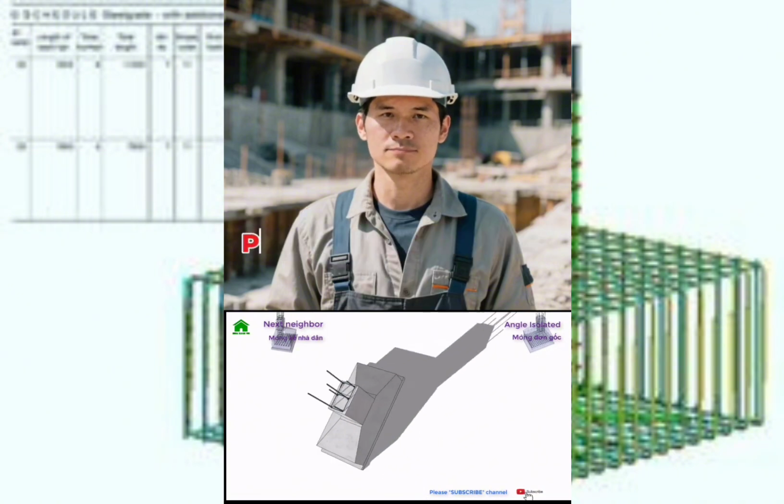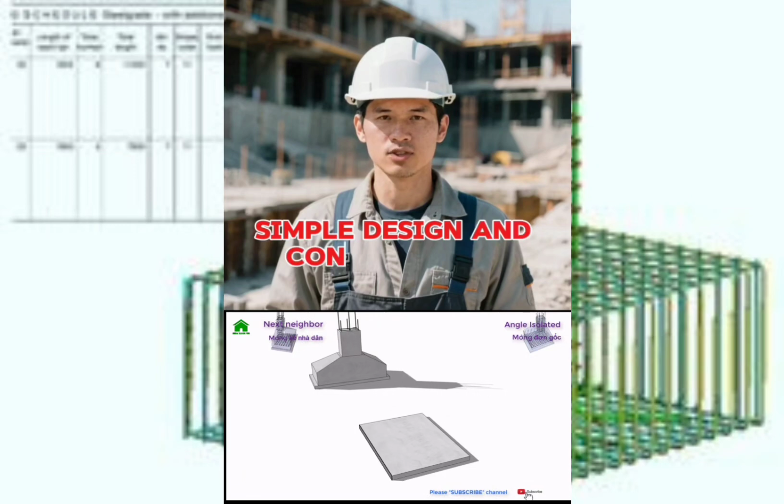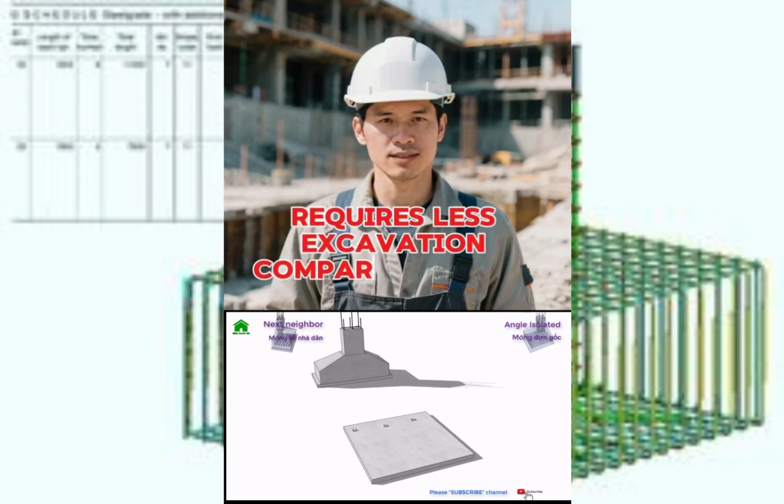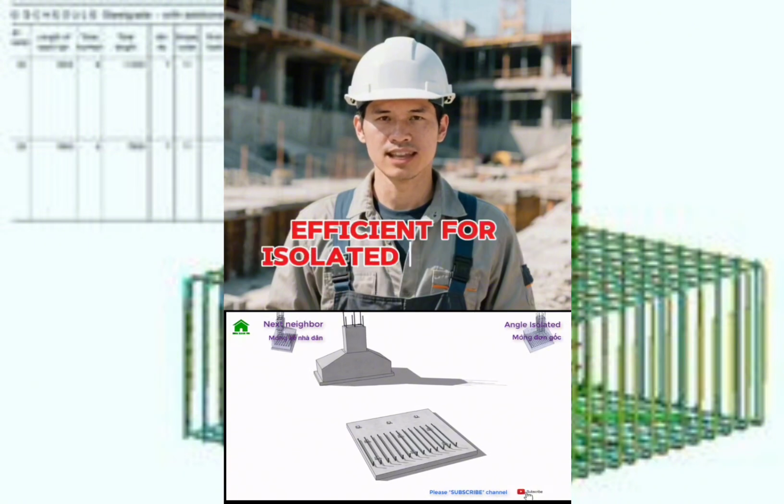Advantages of pad footing. Pad footings offer several benefits. Cost-effective for low-rise buildings. Simple design and construction process. Requires less excavation compared to deep foundations. Suitable for soils with good bearing capacity. Efficient for isolated column loads.